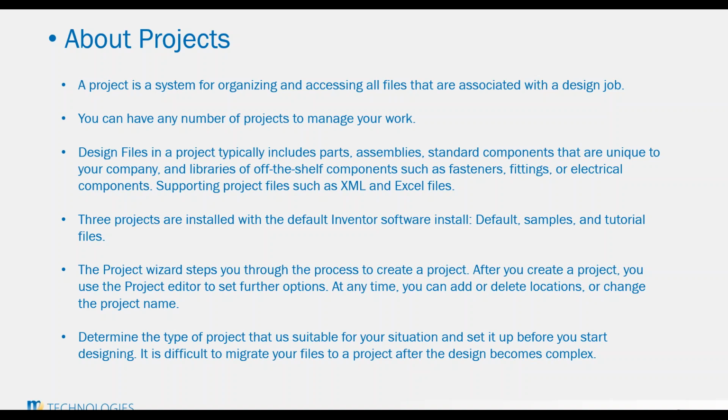Within the project file wizard setup, you can set all of the defining paths. At any time, you can add and delete locations from the project file. In order to do this, you actively have to close down all files open in Inventor before you can edit your project file. If you try to edit your project file within an open drawing or any open documentation, there will not be options to save, or they will be grayed out.